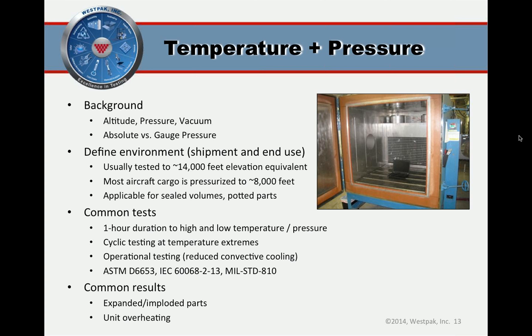Herb? Well, thanks, Mike. The altitude above sea level is, as Mike said, a substantial factor in the density of air, and thus its ability to hold the heat and then to dissipate the heat. The ability of a heat exchanger to properly cool a product can be grossly compromised at altitude. Therefore, any product that is air-cooled should be tested at healthy levels where people actually use the product. Levels often include 7,200 feet for a kind of a normal level. That's where Flagstaff, Arizona is, by the way. And extreme levels going up to as high as the 14,000 feet, as Mike mentioned.